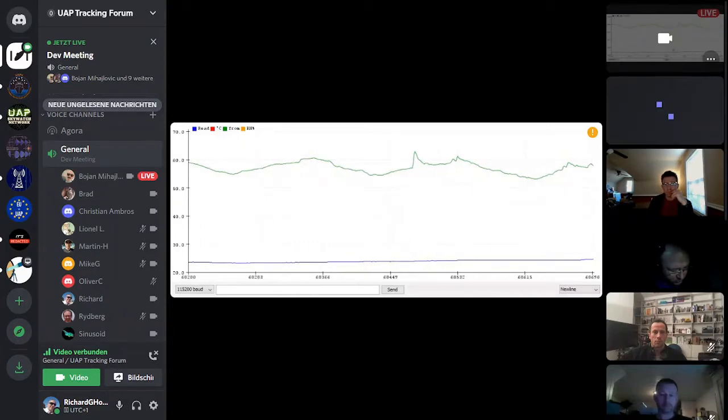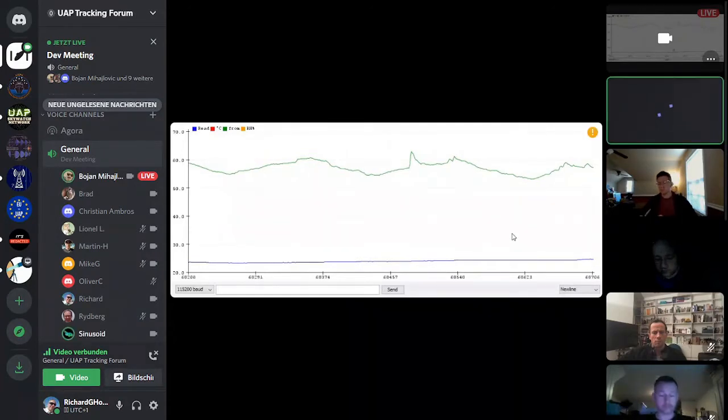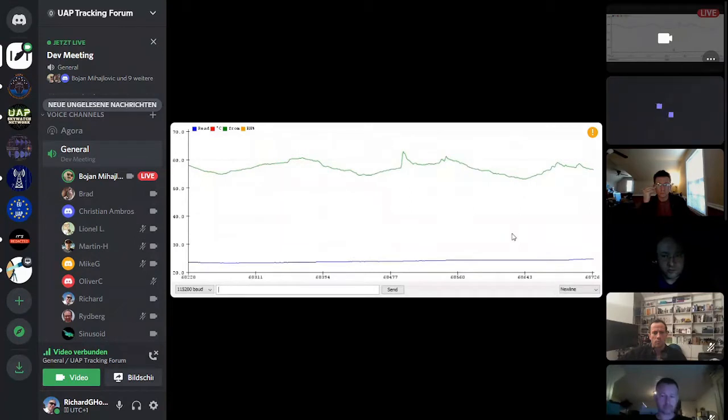Because the reading you see on the right side is coming in, and after a while it will be very stable. So it reads every 2 seconds. This is my problem with this sensor: if you put it close to a fan, or if you have airflow inside the box, this is somehow going to hurt the reading on the humidity sensor.